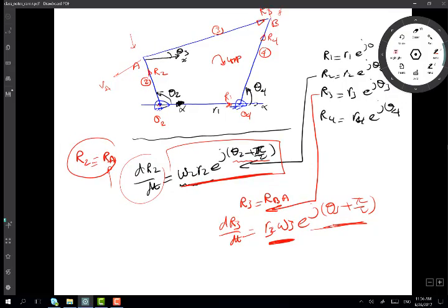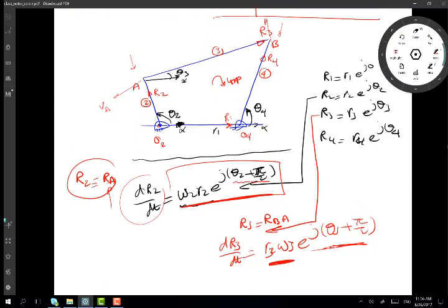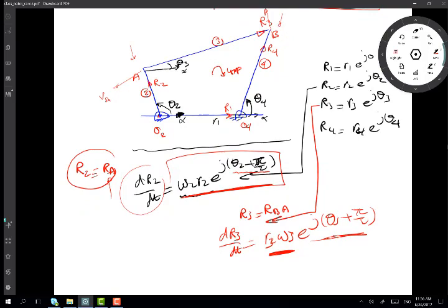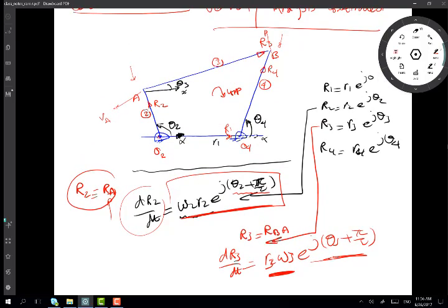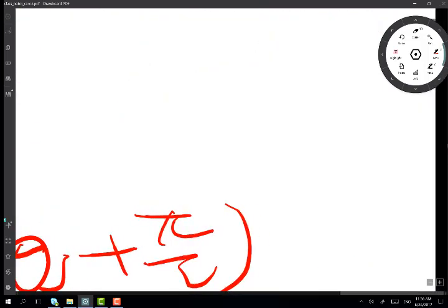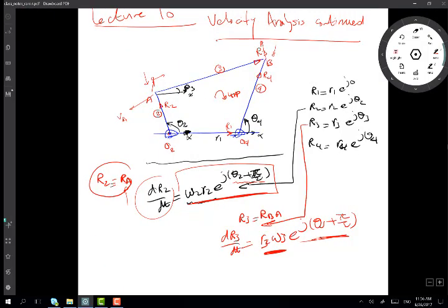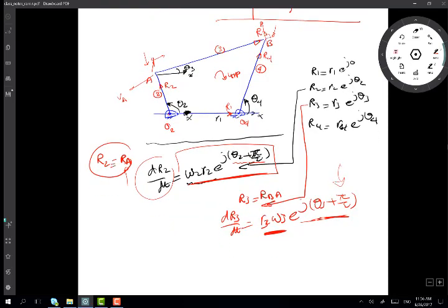However, this time around, this vector is only a relative one; it does not give me the absolute or real velocity of point B, just the velocity of point B from the point of view of an observer standing at point A. This relative vector is still perpendicular, as we agreed, because it is 90 degrees, right?